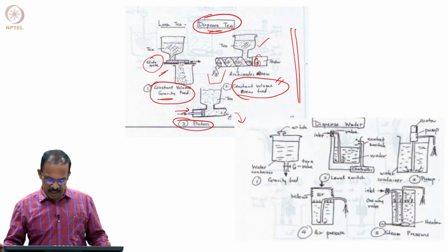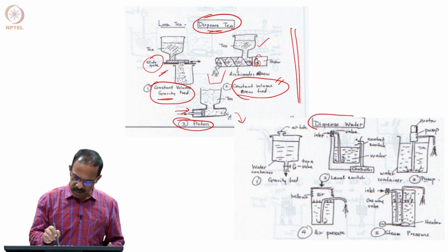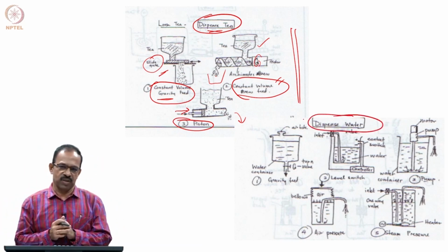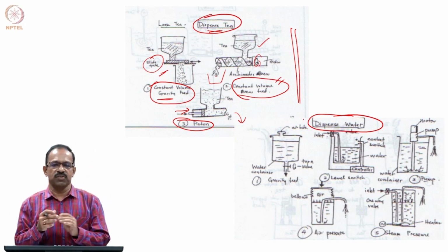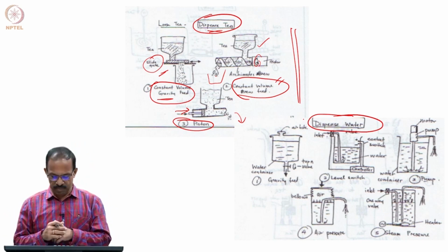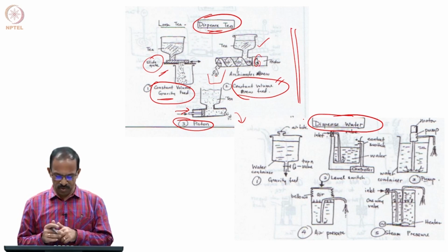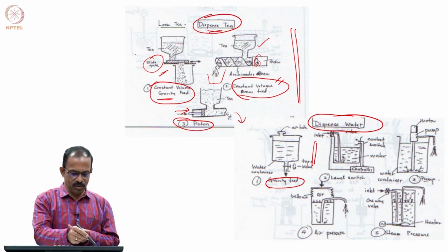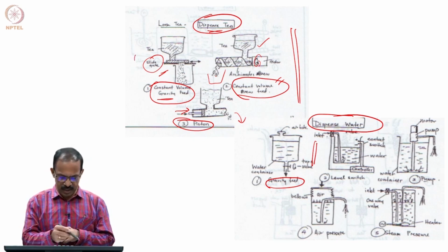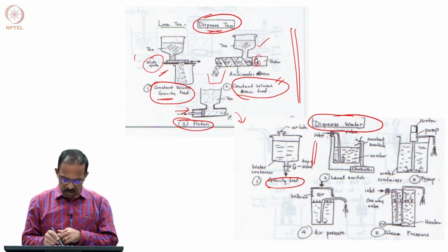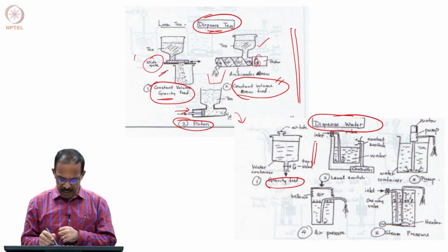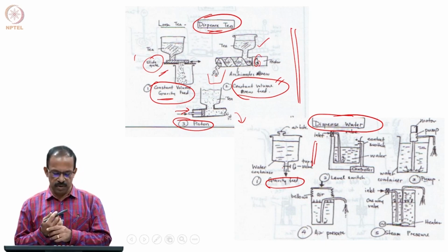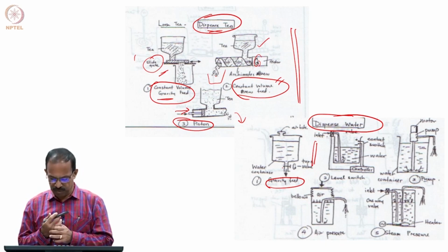And another example, another function, suppose it is dispense water. So, dispense tea is a function, dispense water is a function. Again you want to dispense a fixed quantity of water for making tea. So, what are the ways in which you can do this? You can do a gravity feed, as you can see here, something similar to the gravity tea dispensing. Here is a gravity feed, a water container and a valve. You can control the valve and then get the flow. It is a very common way of doing it.